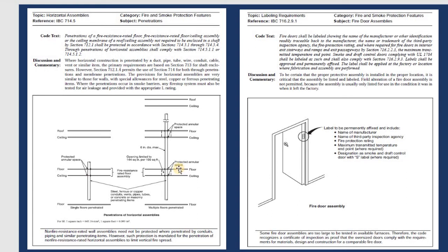In some of the section cuts, you can see protection between both sides of the vertical one, and after that, in the horizontal, you need to do the same thing for the ceiling and the floor. You see both sides need fire ratings, and on the vertical one, the space between them you need to protect against fire also.